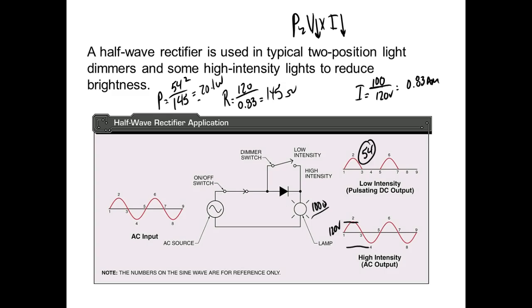A device that's designed to run off 240 volts is designed to run off 240. If I plug that device into 120 volts, it'll probably burn up, not because your motors won't start. They can't create enough torque, and the motors will probably burn up if you don't have an overload.